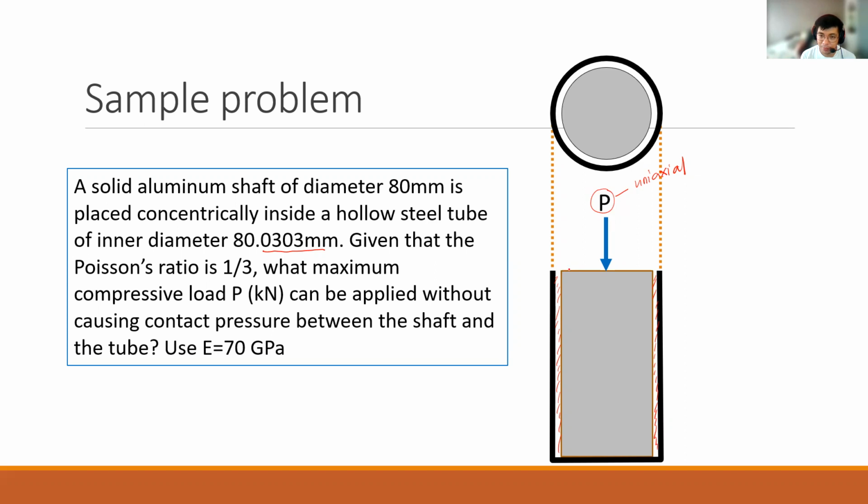So of course the contact point is this one here, the cross-sectional area on top, which is a circle, di ba? Since we are looking for the expansion on x, if we go back to the formula, nu, the Poisson's ratio, is equal to, the numerator is the other axis, di ba? The transverse axis. This time, the transverse axis in our problem is the x-axis, since that is the one expanding due to the vertical load. So this one is negative epsilon sub x.